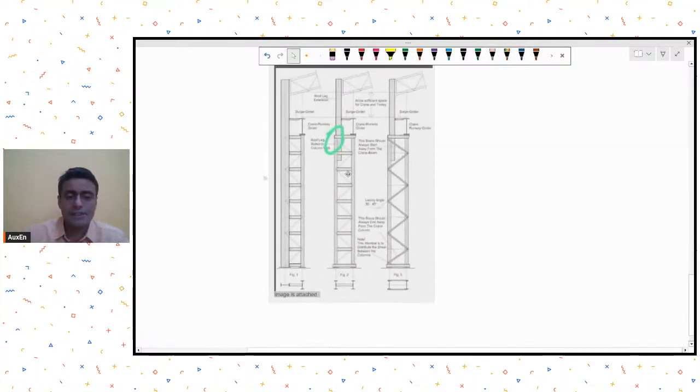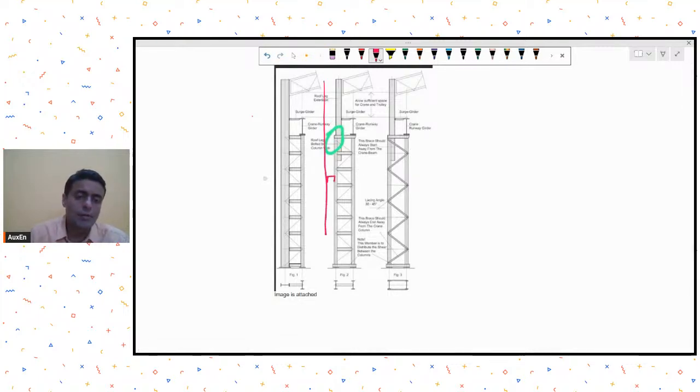His question was that suppose he has this case where he has a stepped column, and due to some reason maybe there is an offset on the outer face, and now he wants to fix a sheeting over here, but due to this offset, how will he manage? That means if I'm going to provide a girt over here, I may require a larger girt over here to manage my connection with this column roof leg. Why? Because this roof leg was at an offset, and because of this offset, I would require either a longer or a bigger girt, but generally we don't do that.